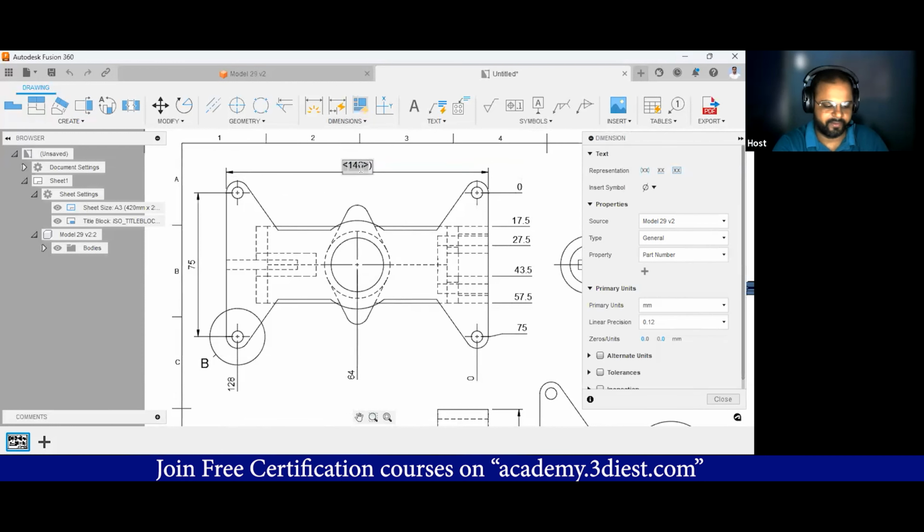Also, we can select any dimension, just double click on it, and here is an option called reference dimension. Just activate that. It will automatically put that dimension into parentheses. Here you can see this is how you can create a reference dimension. Wherever we have included these small brackets, this means that these dimensions are reference dimensions, just for the overall purpose, just for reading, not for manufacturing. You will not use these dimensions for manufacturing purposes, right? So this is the purpose of a reference dimension.